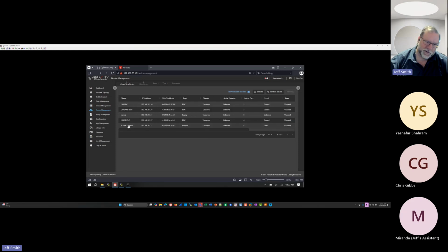The other thing you're going to get in Rockwell PLCs in particular is, as the network is brand spanking new, they just fired this up, but it's going to go out and interrogate these devices. So before too long, I'm going to see the serial numbers, the firmware revisions, what the device has on it in terms of those types of details. So I can come in here and manage devices. I can quarantine devices. I could create a zone called quarantine. And when there are devices I don't want on the network, I can do that.